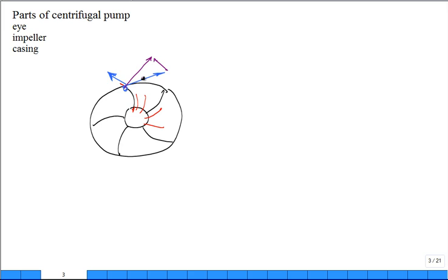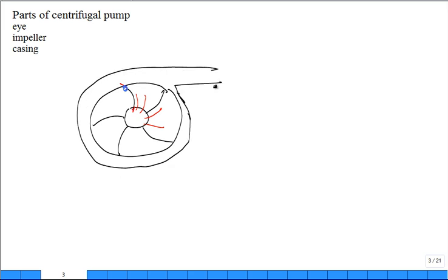Off those impellers, okay? And then, get rid of that velocity diagram, it's caught in a casing. Here we'll put the casing, maybe we'll start it here. It'll be very small, and then it'll get larger, larger, larger, larger, until you discharge. And there's a cut right here, okay? Because it's accumulating, accumulating, accumulating, getting more and more. That's why it has to increase in size.